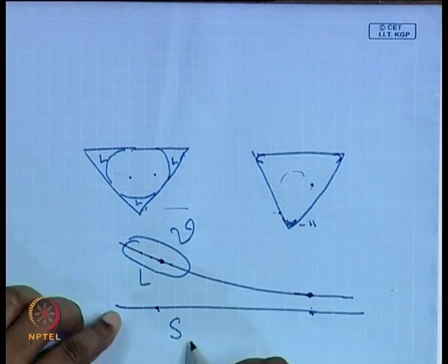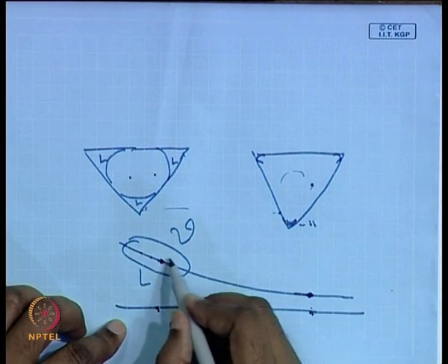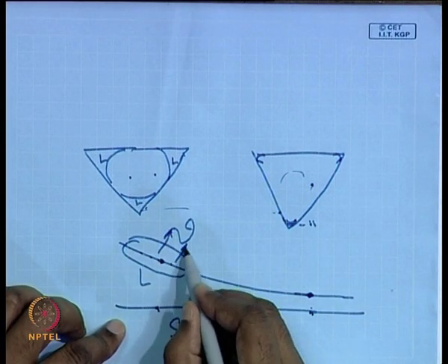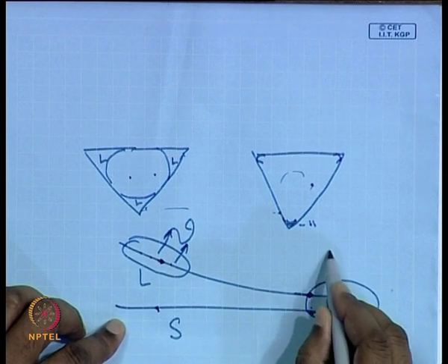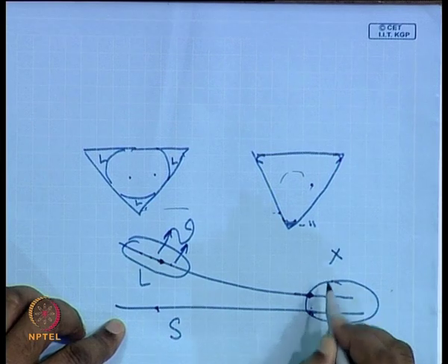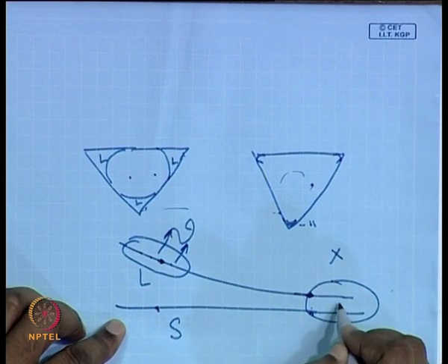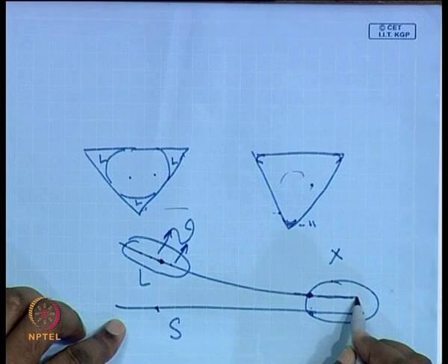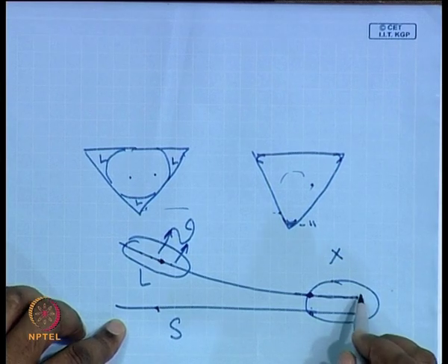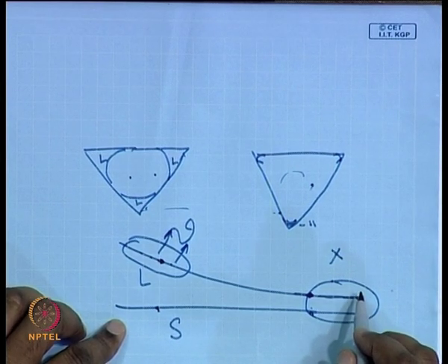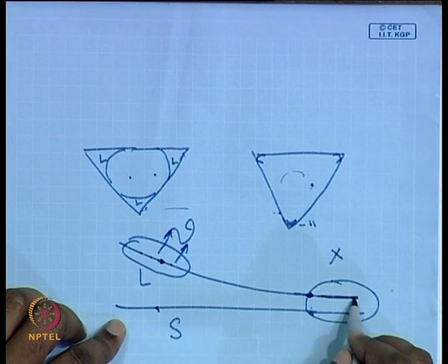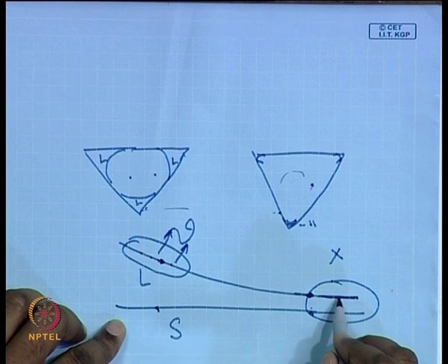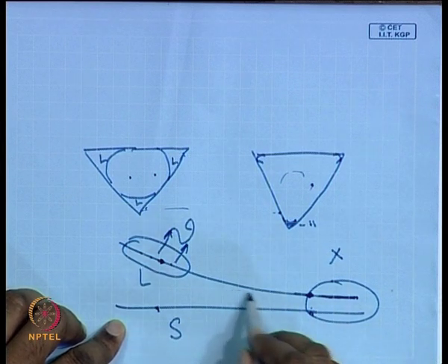So, therefore, if I hit this solid, there is definitely evaporation possible from here, but over here the molecules are so strongly bound that I will not have any evaporation from this region. So, this is called the adsorbed thin film region, which could be about hundreds of angstroms thick, but it is going to play an extremely important role to define or to govern whether or not you have a wetting system